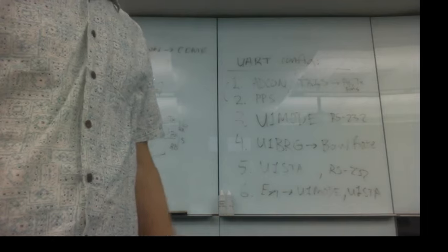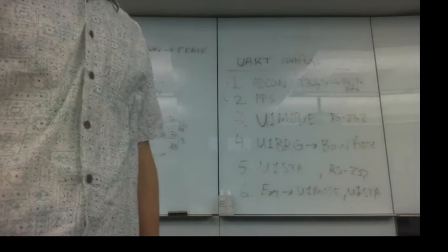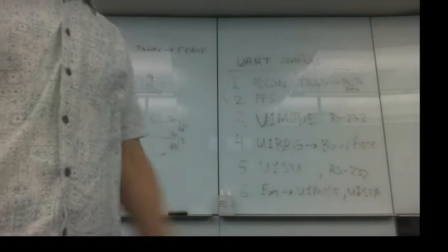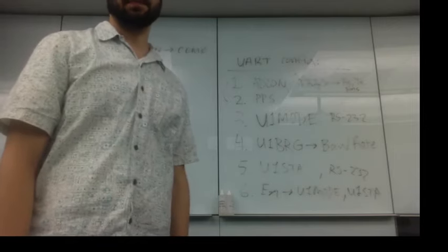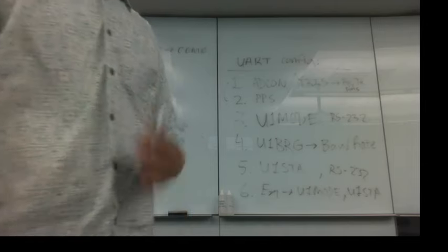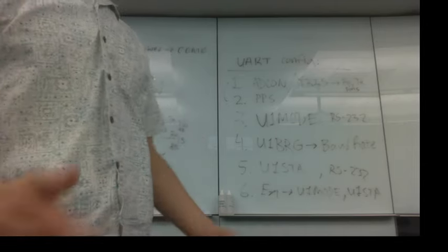All right, so this is on the PIC side of things. So we talked about the mode register. There's a lot of bits in there. The top one, bit 15, is the UART enable. It enables the UART module.